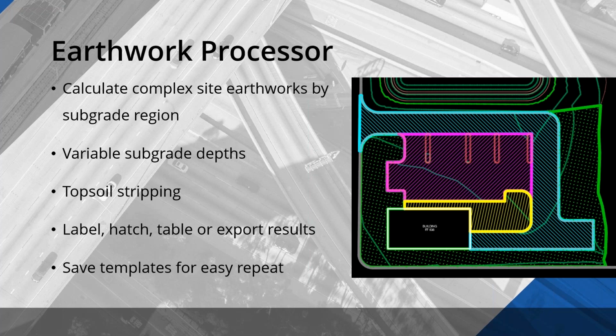And finally, a lot of times the way you define this, be it cut factors, what defines your earthwork definition, your earthwork set, can be repeated from one project to the next. So much like many of the other tools in the CIM Project Suite, you can save out templates that can be reused in other drawings or in other projects.